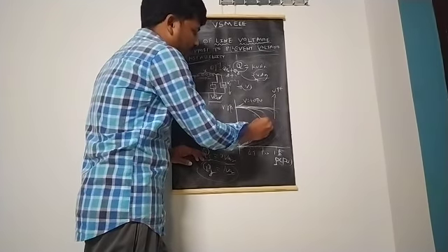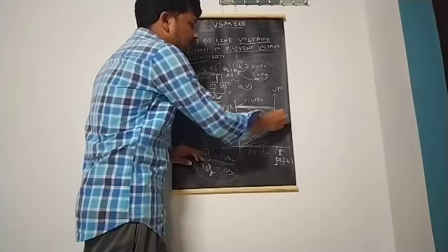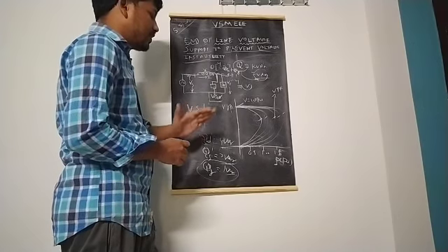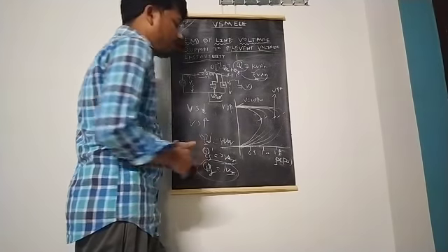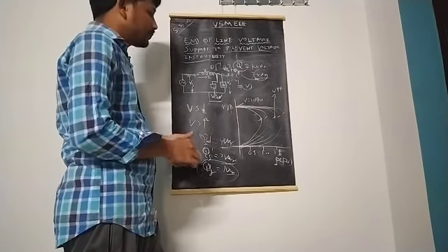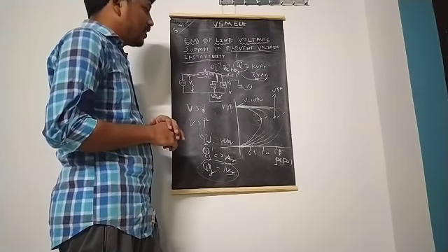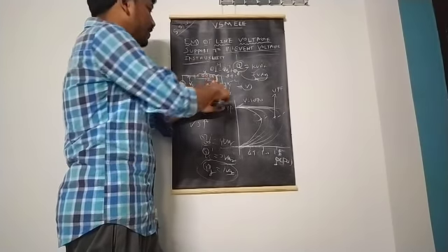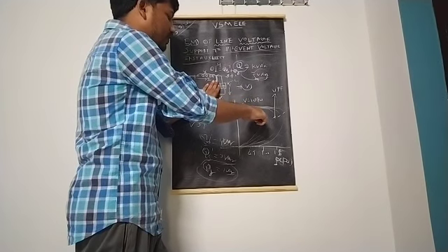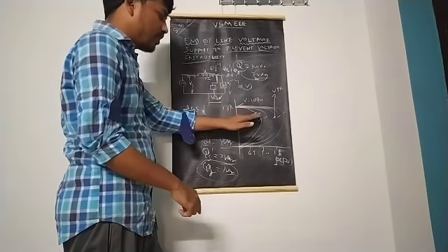The same happens at different power factors, for example 0.85 lagging and 0.95 lagging. This is the unity power factor. This is 0.97 leading, and this is 0.9 leading. Depending upon the power factor, the voltage changes with respect to load. That means load and power factor decide the voltage profile of the system. One thing you can clearly observe is that without any compensation device, while increasing the load, the voltage decreases up to the critical point. After the critical point, the voltage decreases at a much faster rate.